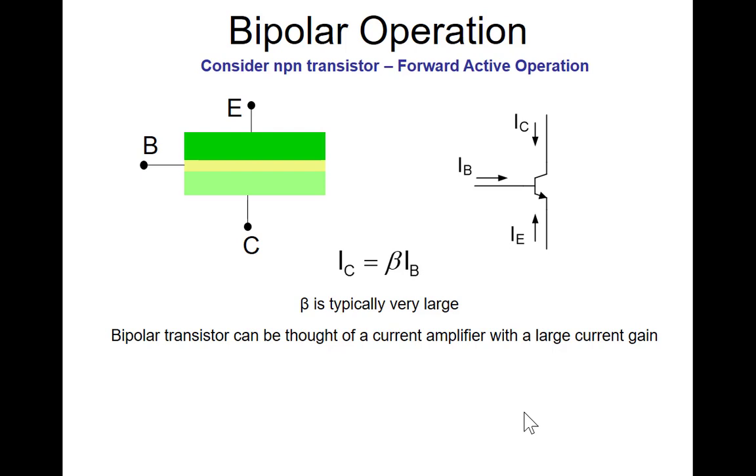If you think of a MOS transistor operating in the saturation region, what can it be thought of as? With an expression. So this represents the relationship between the port variables at the base and the collector. If you look at the MOS transistor in the saturation region, the drain current is equal to mu Cox W over 2L times (VGS minus VTH) squared. So the controlling variable is the gate to source voltage, and it controls the current.